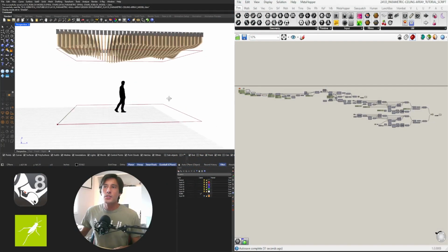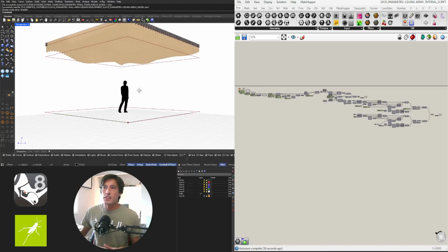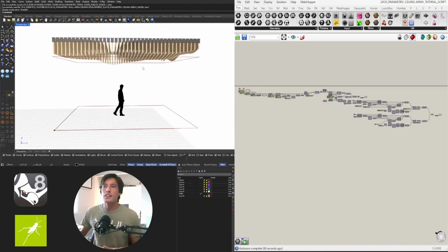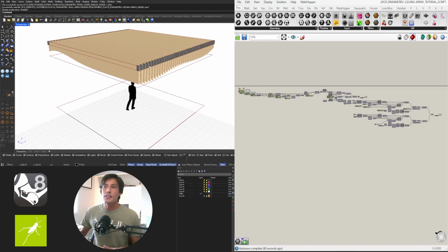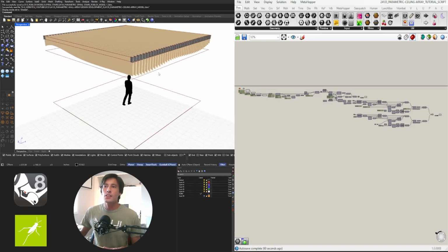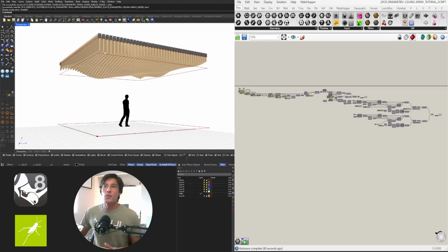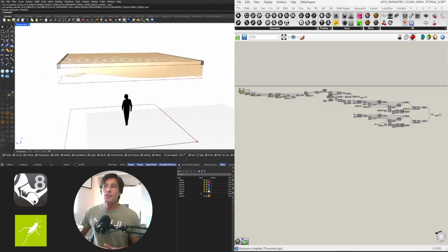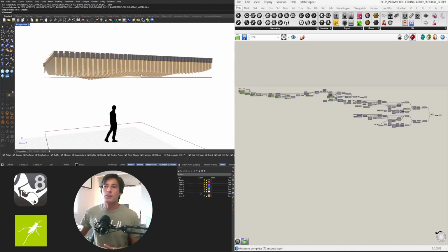In today's video, you'll see a full tutorial where I'm going over all of the steps for creating this design. This is a wavy ceiling design that is an array, and at the end, you'll see that we also create the clips. So it has two different tutorials in one. First, how we create the form, create the array, create the depth for the contours, and then, like I said, the clips for hanging these onto a wall or part of the structure.